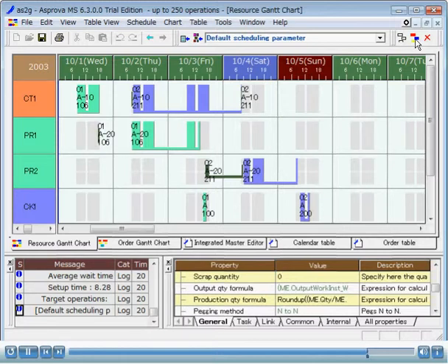We can specify values for the above suspend time max using those properties for each resource. The production time of process CK for order 02 in the above figure indicates suspension. Also, the setup in process PR2 includes suspension. For PR2 and CK1, let's specify the production suspend time max and setup suspend time max as follows in the Settings tab in the Properties window.